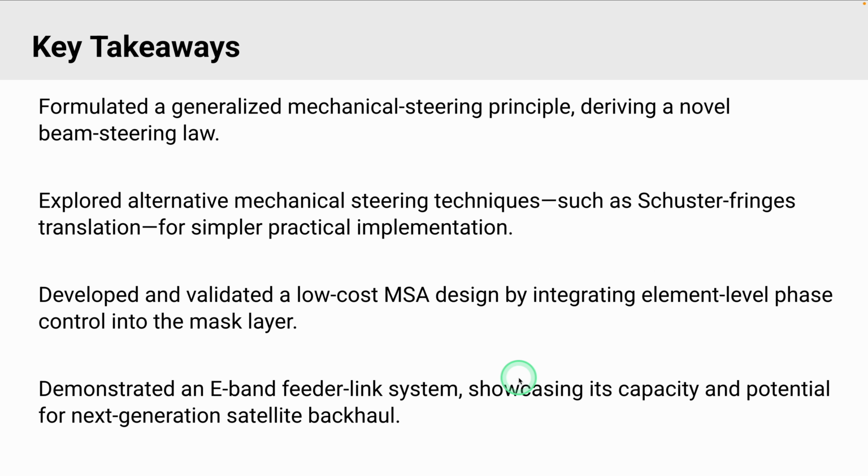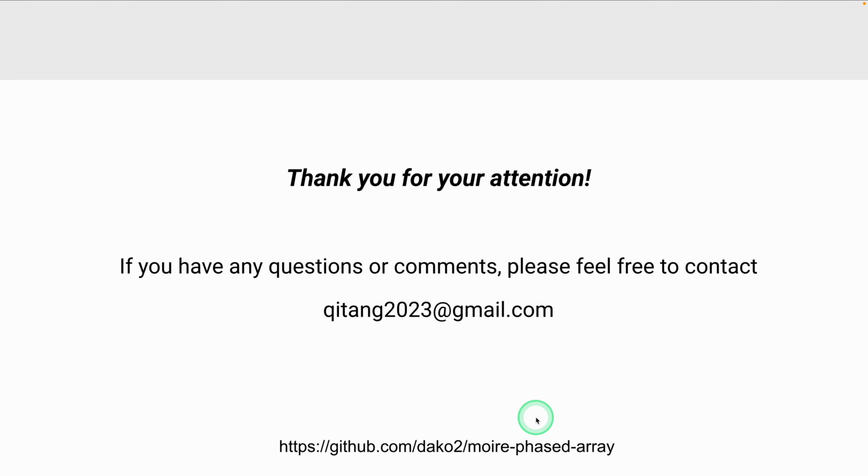In summary, we formulated a generalized mechanical steering principle, deriving a novel beam steering law. We explored alternative mechanical steering techniques such as Schuster fringes translation for simpler practical implementation. We developed and validated a low-cost MSA design by integrating element-level phase control into the mask layer. And we also demonstrated an E-band feeder link system, showing its capacity and potential for next generation satellite backhaul. That's all the talk, and thank you for your attention.